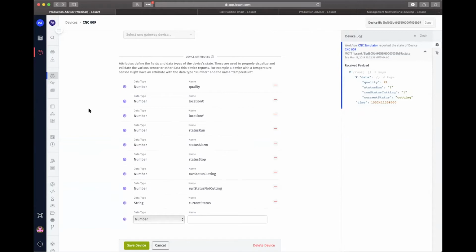And you have control over how much data is sent to the cloud. These machines can report once a second or even faster with all of their information, but that's not practical for a cloud environment. So you may want to have your edge compute device send the information up to the cloud once a minute or whatever you think is appropriate for people to see the information. And of course, if there are any alarms detected by the edge compute device, that information gets uploaded to the cloud immediately so that we can process it.